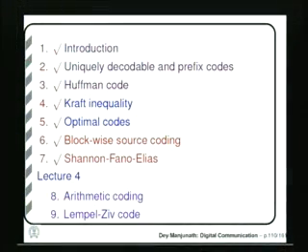coding, why it is possible to do source coding for most of the practical sources, and then we have classified different source coding techniques, especially desired source coding properties. We have seen that we should have uniquely decodable code, so that we can decode any encoded string uniquely in the destination. And then we have seen that even all uniquely decodable codes are not always instantaneously decodable. So, to have instantaneously decodable code, we should have prefix code, so that no code word is a prefix of another code word. And we have seen so far 2 source coding techniques.